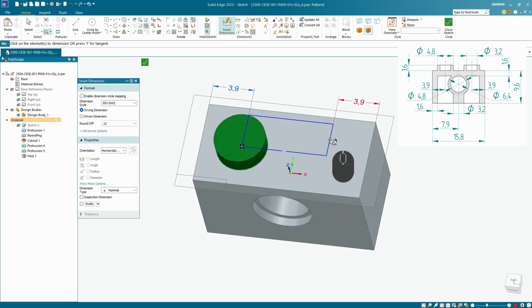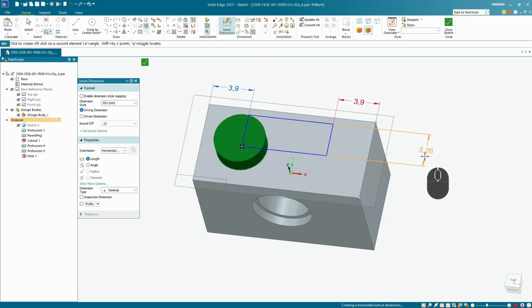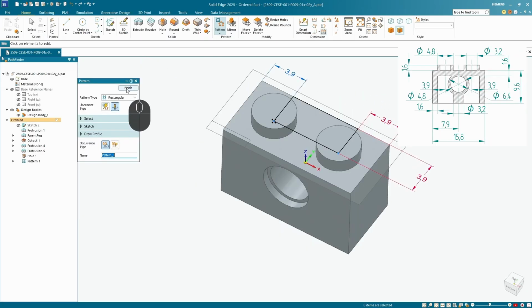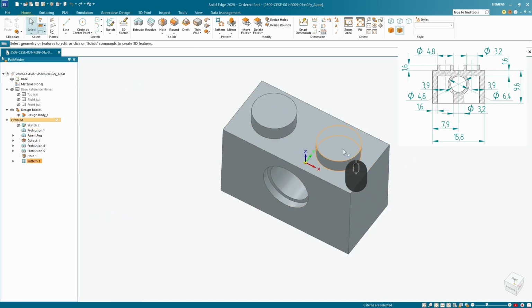And again, the width of our block here, because we're only doing this for one peg wide blocks, is less important. I'm going to type in 3.9, but that's not something we expect to have a peg on this corner of the block or along this line of the block at all. So I'm going to close this sketch and click finish. And there's our two pegs.